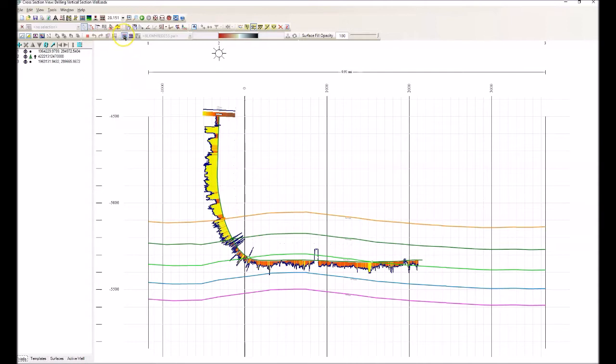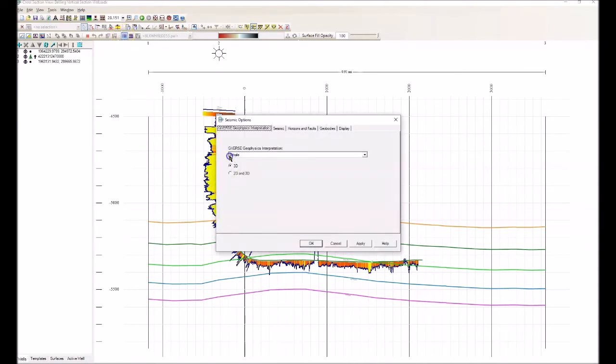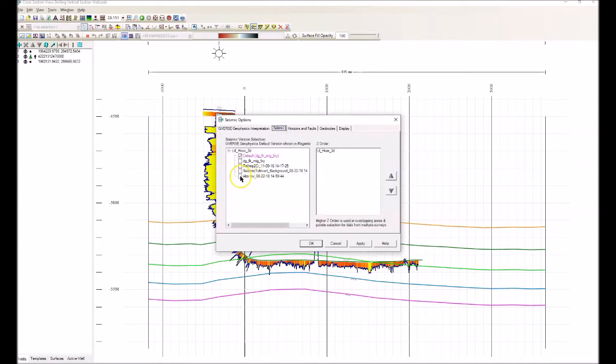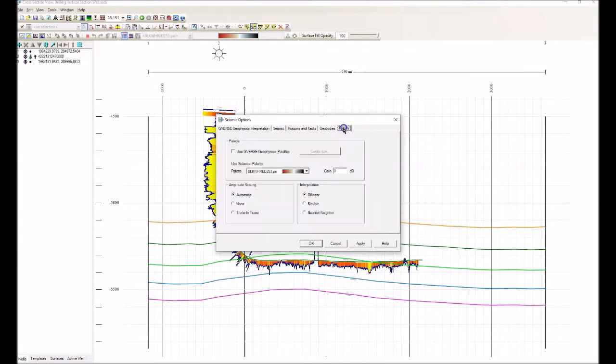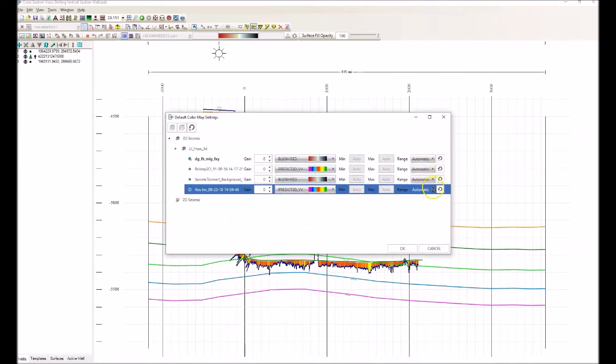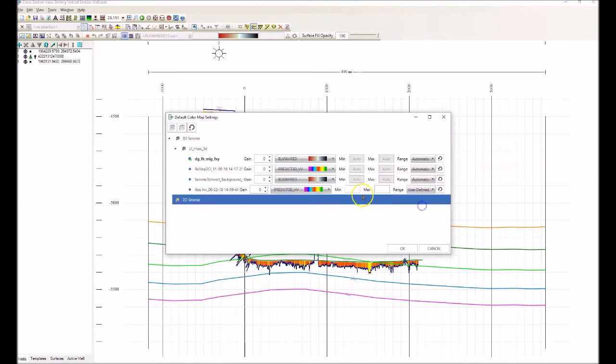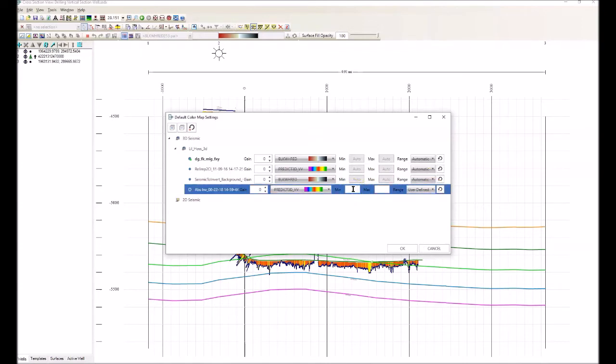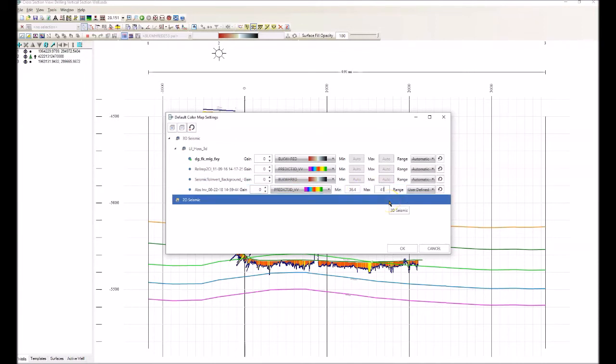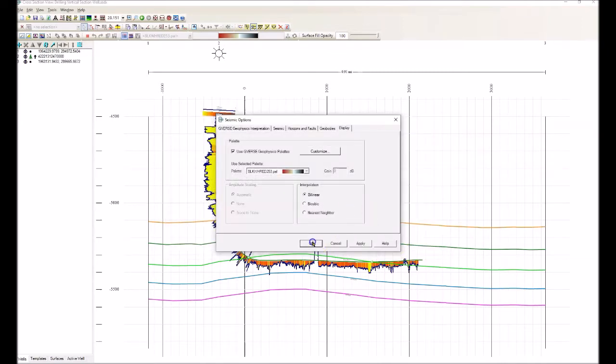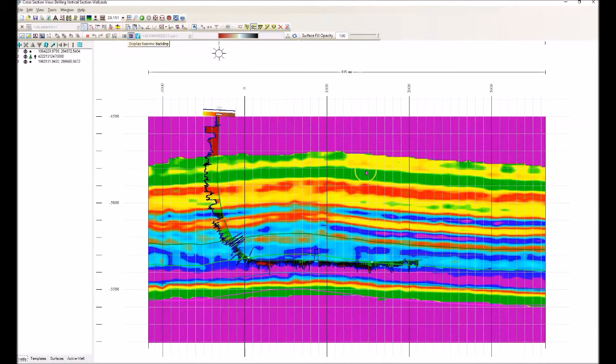And let's set up the seismic backdrop. We are hooking into the B-Shale GVERSE geophysics interpretation. For the seismic, we're going to be using the absolute inversion that we used in GVERSE Geophysics. And for the display, we're going to use the same palette that we're using in GVERSE Geophysics that we saw on the 3D probe. And we're going to set the range that we determined over in GVERSE Geophysics of 36.4 up to about 40. And let's turn on the seismic backdrop.